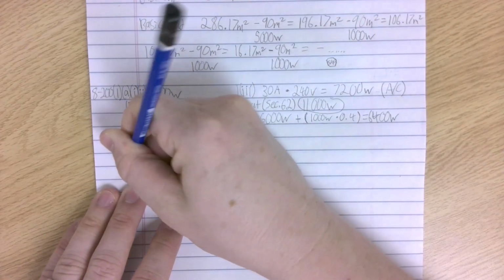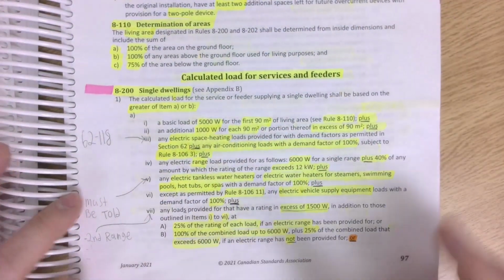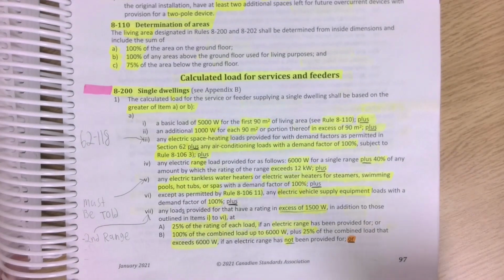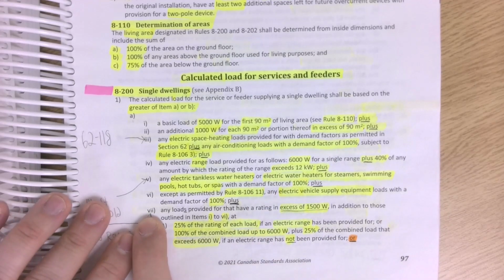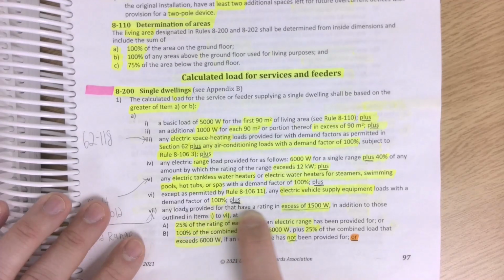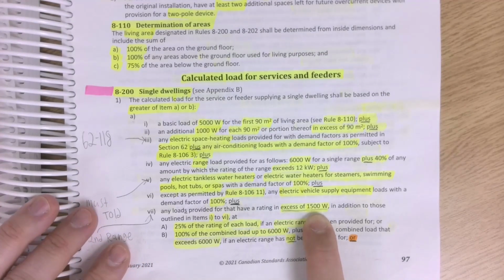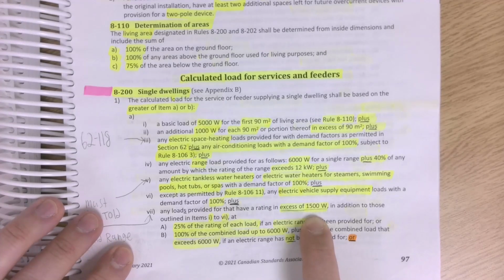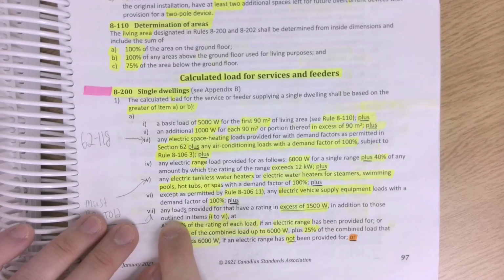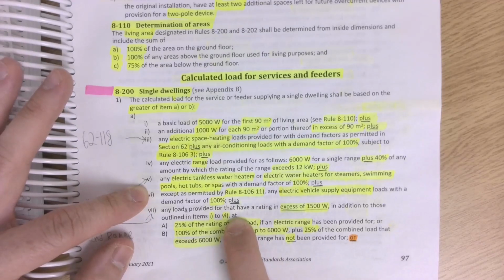Then our last item for this calculation, VII, or 7. Yep, probably 7 for my Roman numeral reading. We've had all these specific loads and calculations and demand factors, and then item 7 is going to say any loads provided for that have a rating in excess of 1500 watts. So 1500 watts is not in excess of 1500 watts. Might sound like I'm repeating myself, but 1501 watts would be in excess of it. In addition, added to those outlined in items I to VI. So all this stuff we've done so far, plus everything in excess of 1500 watts at 25% of the rating